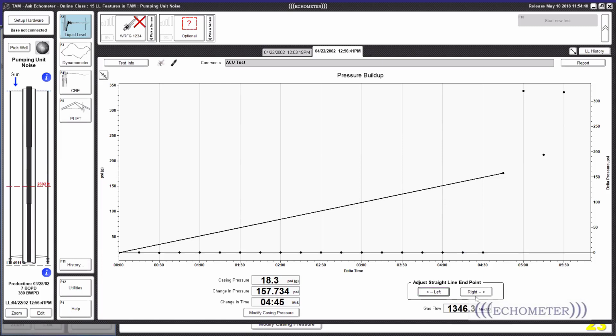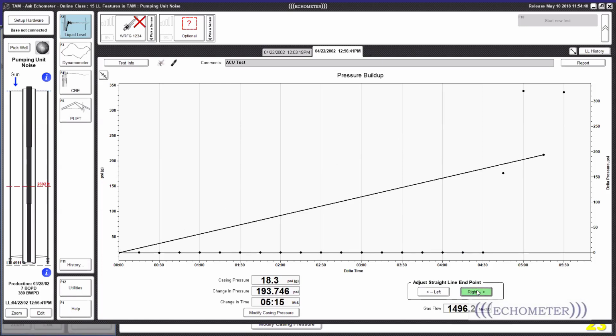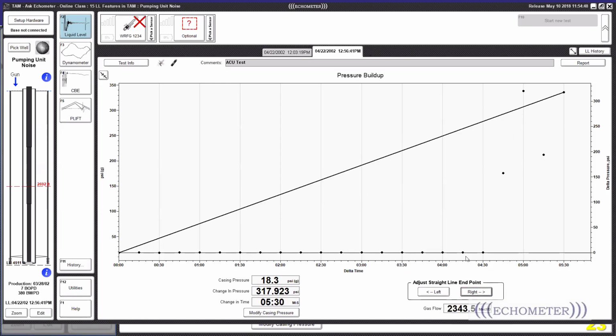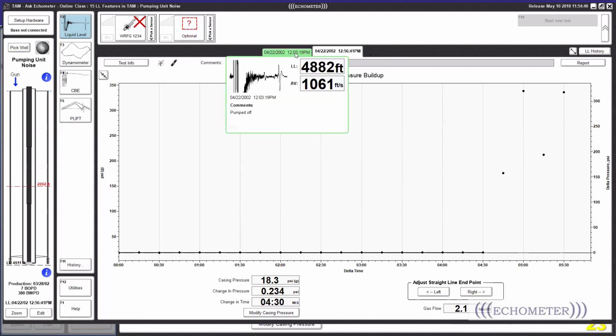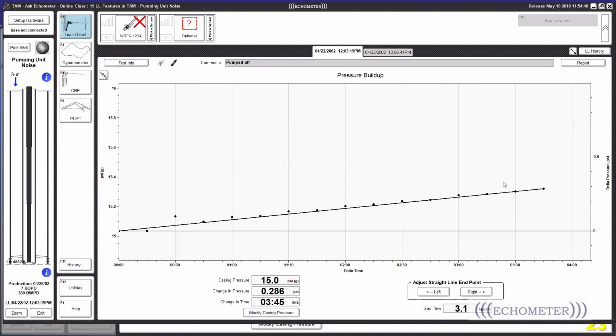This fluid, so if we just record the data and we ignore that, of course the liquid percentage calculated will be extremely low. This is more a gas well, so this is not true. So even if we have only this shot, we can save this shot and bring this point back to a normal place. Or if we actually do two fluid level shots, we would probably use the first fluid level that has a better pressure buildup.